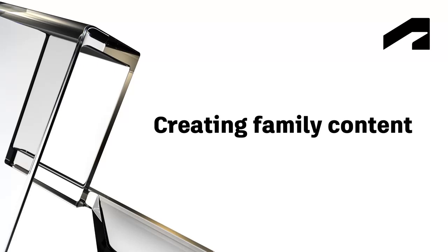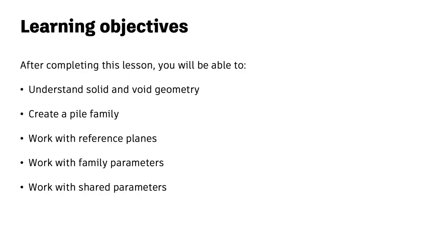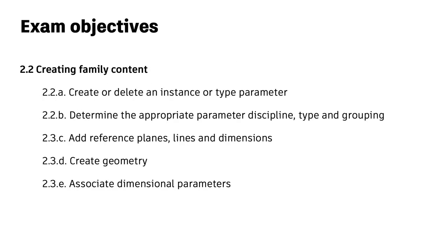After completing this lesson, you will be able to understand solid and void geometry, create a pile family, work with reference planes, work with family parameters, and work with shared parameters. The objective domains covered are 2.2a, create or delete an instance or type parameter, 2.2b, determine the appropriate parameter discipline, type and grouping, 2.3c, add reference planes, lines and dimensions, 2.3d, create geometry, and 2.3e, associate dimensional parameters.